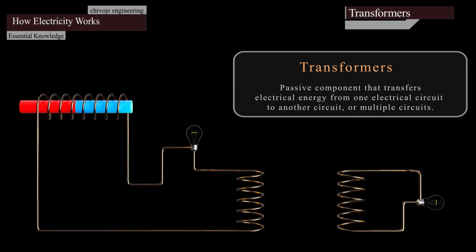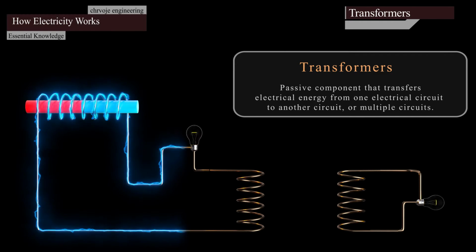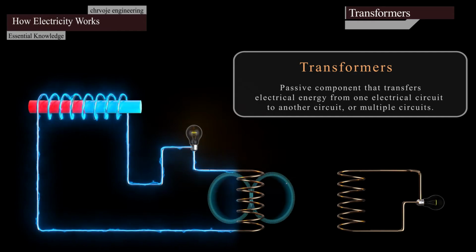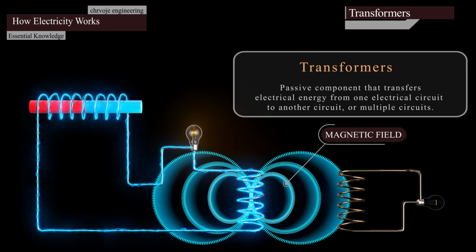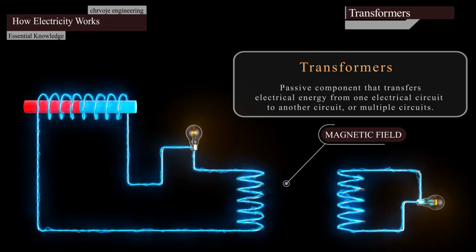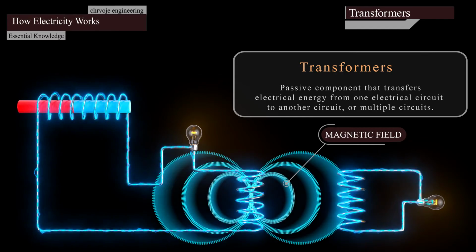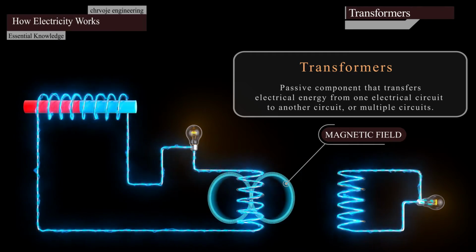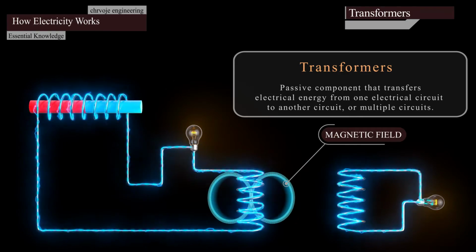Generally, the primary winding of a transformer is connected to the input voltage supply and converts or transforms the electrical power into a magnetic field, while the job of the secondary winding is to convert this alternating magnetic field into electrical power, producing the required output voltage. Now, what's important about the transformer is that we can increase or decrease the voltage between the primary and secondary coils, simply by changing the number of coils on either side.